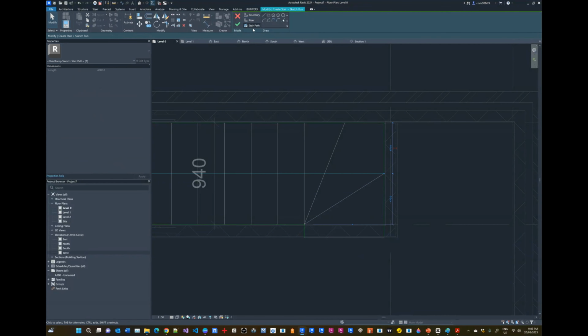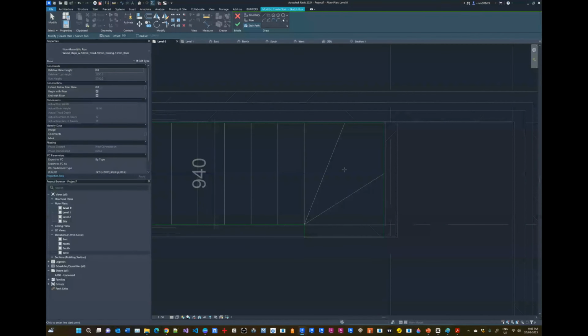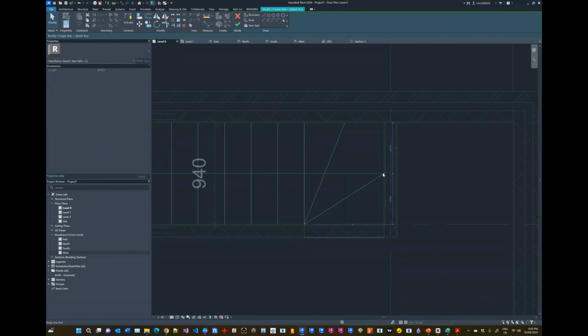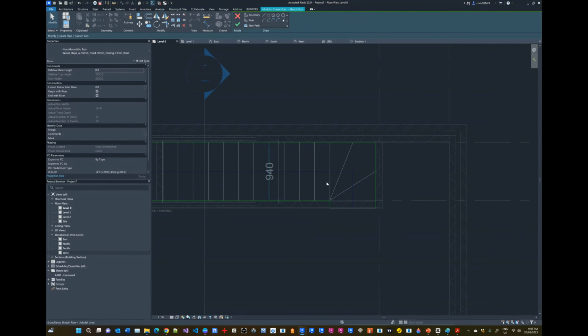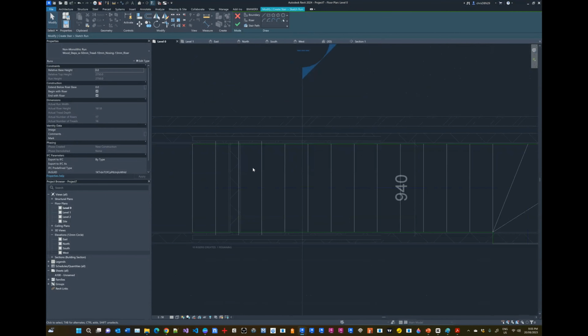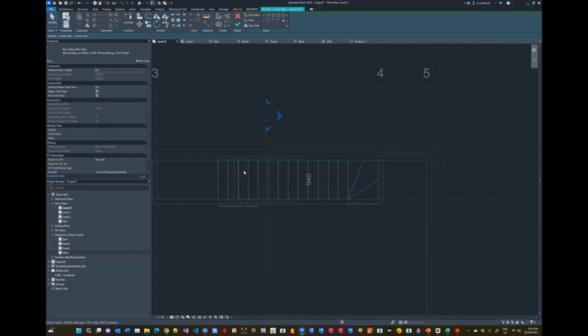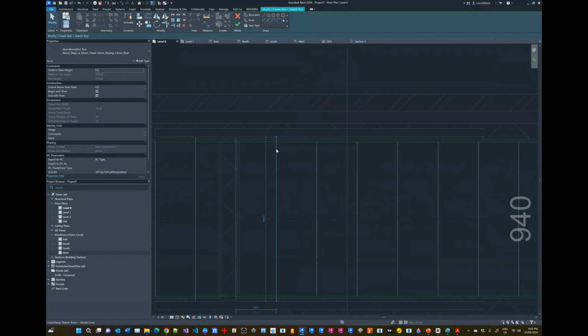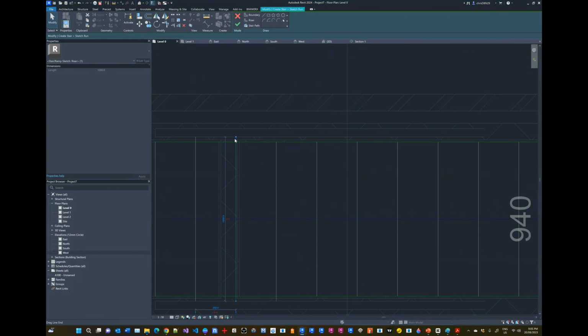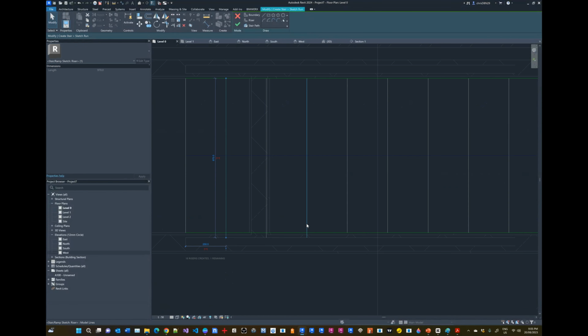And now finally we need to change the stair path. So this path has to go to the center here. So what I'm going to do is I'm going to create a new stair path from this center where it intersects this line. And then I'm going to select this one. First I deselect everything, of course, and then I'm going to draw that back. Okay, now we've got a staircase running up here. We're going to have a problem with these risers going outside of the boundary here. It's going to complain about that, and I still need to fix it up. So for now, what I'll do is I'll just quickly trim these back, and then we're going to switch to the second level and we'll fix the top part of the stairs. So for now, we're just going to do this.